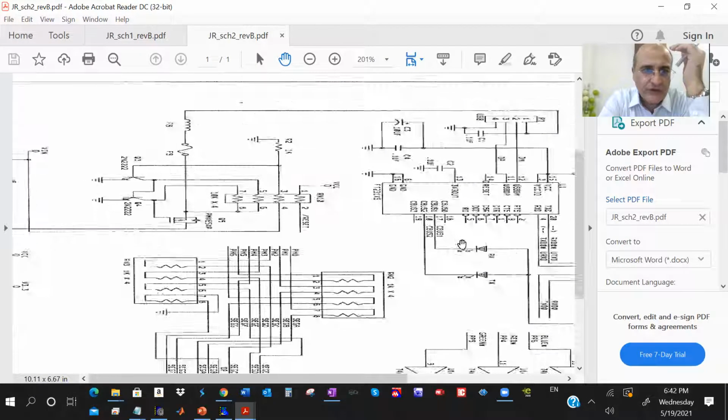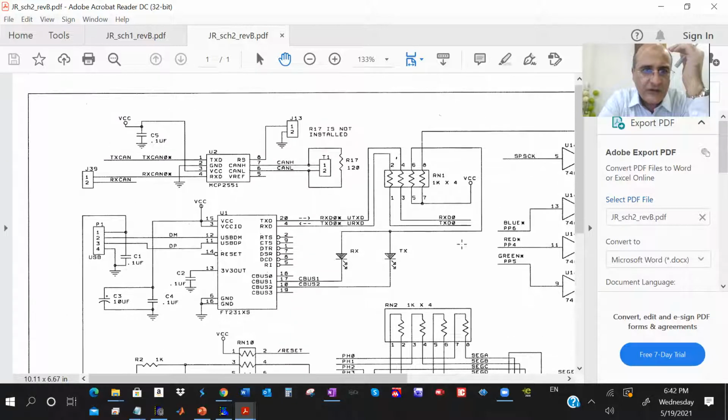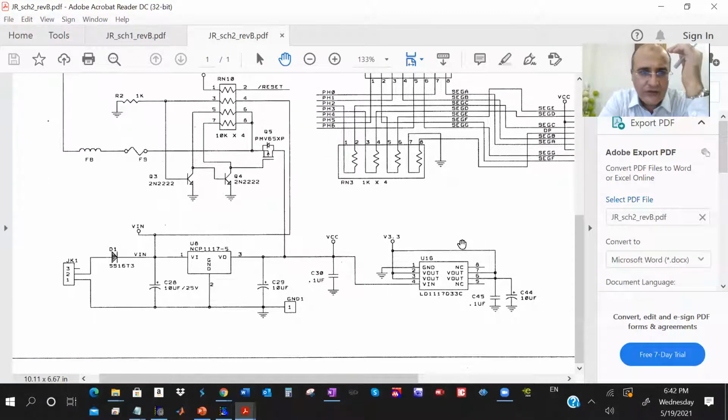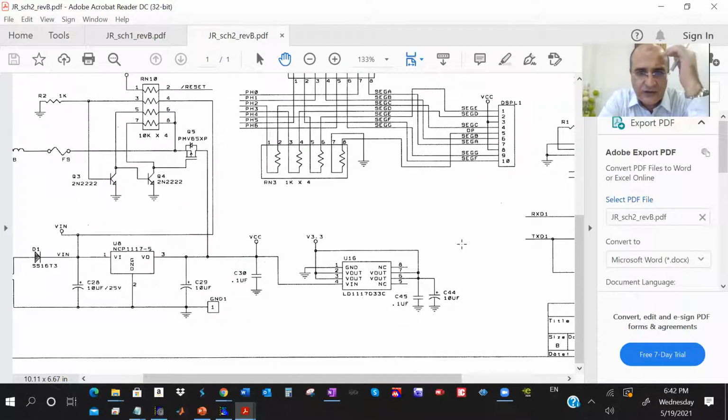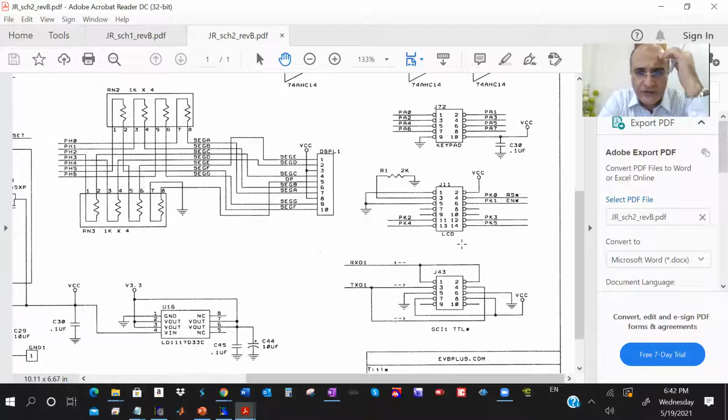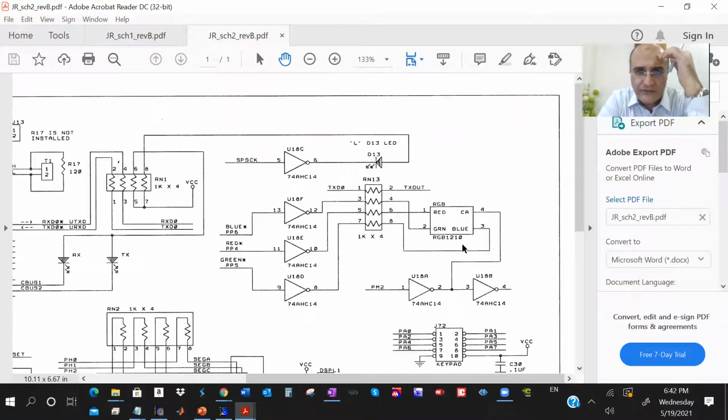Somewhere. Voltage divider: just put the LDR, the light dependent resistor, which is the light sensor, in a voltage divider, and take the voltage to your pin. You can search for it in the schematic.